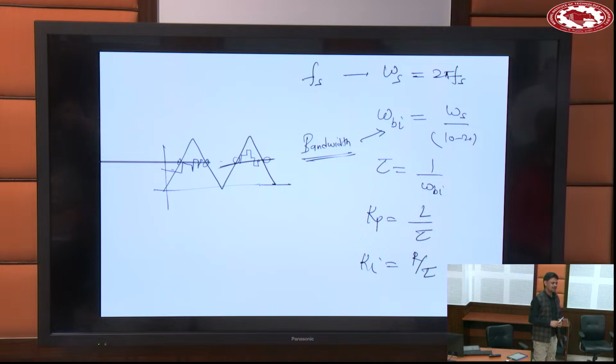Why is the synchronous machine not self-starting? Induction machine is there, synchronous is not self-starting. Why? The rotating field is also there. The point is you are asking the rotor to be Rajnikant, that I say and it happens instantly. After 20 milliseconds, the field goes from N to S, S to N. In 20 milliseconds, the rotor has some definite inertia. It cannot respond. That's why.